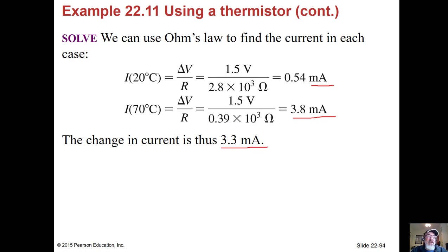And that's how you could take this temperature change that you're getting in the bath and convert it to a current, and then maybe you see that on a meter or something like that, so you can figure out this is what you could measure, and then it's proportional to the temperature change, and you can construct a meter that way.